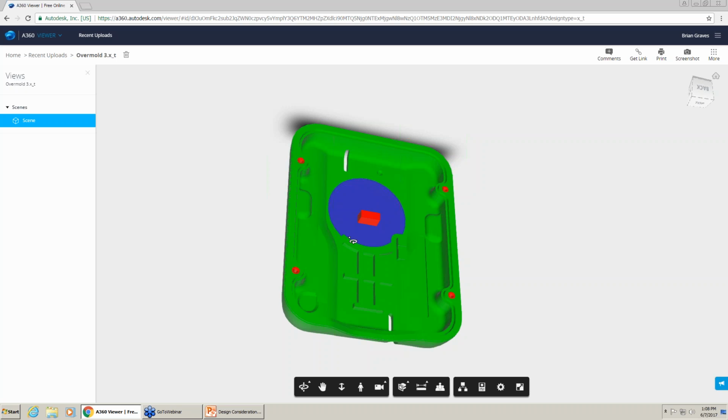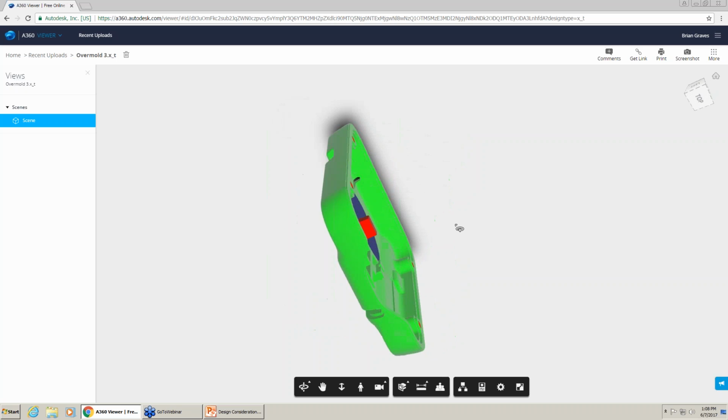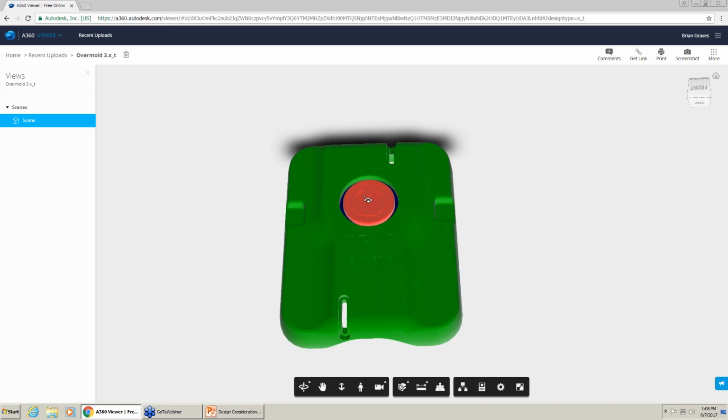And what we did is we came through the bottom and we actually subgated underneath this housing. Came in from the opposite side of the tooling that you normally see a gate, and we filled in this complete area around the button to connect in with the housing. And as you can see, there's a little actuator portion of the button right here, and on the front side, when they push on this button, it moves freely in between, so you don't have friction between substrate and substrate. It allows for just enough pressure, and it's a very cool look. It's a very cool thing that is accompanied with this assembly. Worked very well. This was a good application.